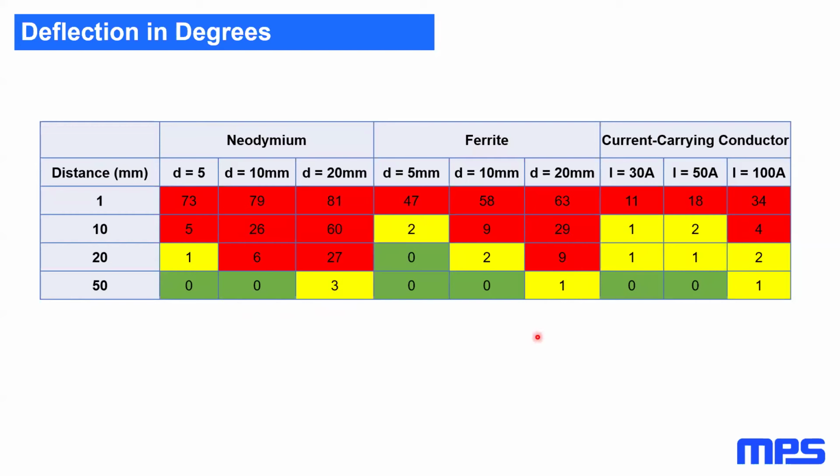I can't remember how many times I've talked to customers where we've had an interference field from, say, a motor. The stator coils have some leakage flux, and we say, well, let's just try to move the sensor farther away from the motor by a few millimeters, and it works. But that's not always possible, and sometimes you have a situation where you cannot move things, or you could have an external motor or an external magnet that could come into the application, and you just cannot afford to have that cause errors.